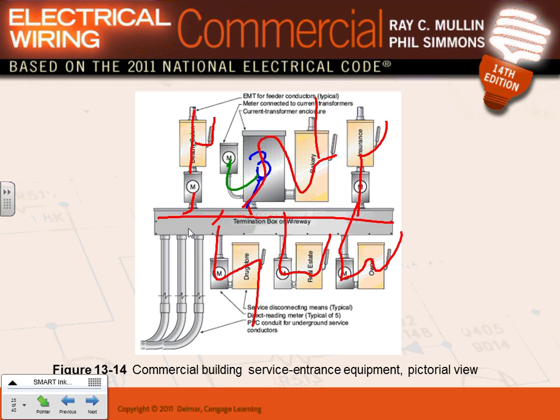So where would you use a system like this? A strip mall, multi-tenant. So how many disconnects? What's the disconnect tool? 6 disconnect tools. Do I have more than 6 disconnects grouped together? No. 1, 2, 3, 4, 5, 6. So if I'm to shut down the power from this section of the building, the code says you can't have more than 6 disconnects.